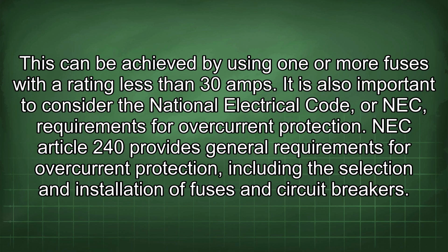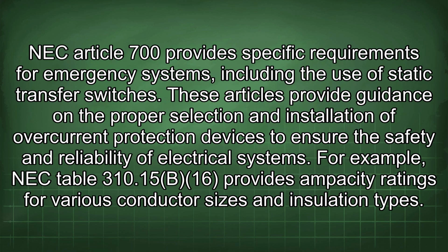It is also important to consider the National Electrical Code, or NEC, requirements for overcurrent protection. NEC Article 240 provides general requirements for overcurrent protection, including the selection and installation of fuses and circuit breakers. NEC Article 700 provides specific requirements for emergency systems, including the use of static transfer switches. These articles provide guidance on the proper selection and installation of overcurrent protection devices to ensure the safety and reliability